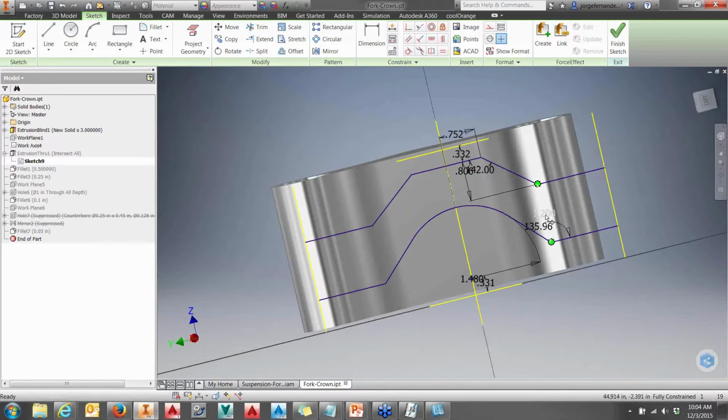And we'll just change this height. Actually, we're not going to change the dimension just yet. What I'm going to do is give it a name. A little shortcut for you guys in case you didn't know: you can actually rename parameters right inside of here. I'm going to do HT equals, for example. And that actually creates the equation for us.